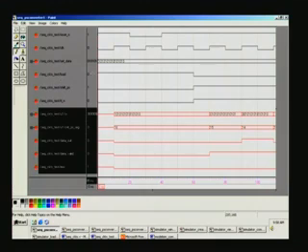With load asserted, you can see that load is high here, and so shifting starts right at this point once the load is complete, and simultaneously you also assert shift right here. This 1010 pattern in the shift register will be shifted 1 bit per cycle at the positive edge of the clock.